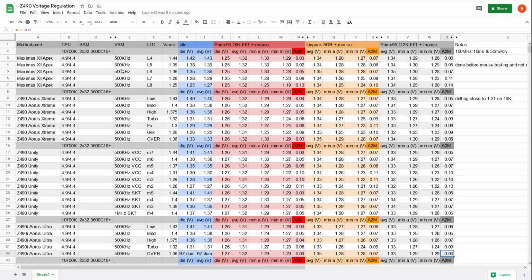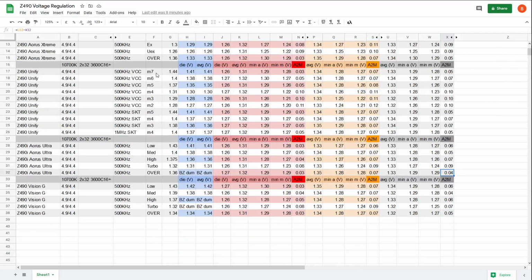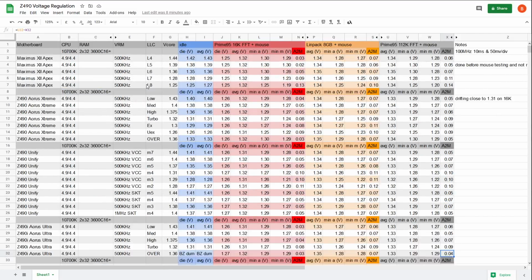But yeah, now I could, well, actually, I think I did it in 2 days for all of these boards. So yeah, I could step up the number of measurements, definitely. But that still wouldn't address the issue that the oscilloscope only goes to 10 millivolts. It would take out some of the uncertainty, but we'd still be looking